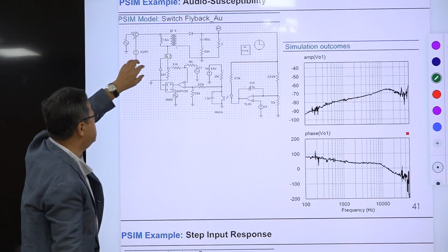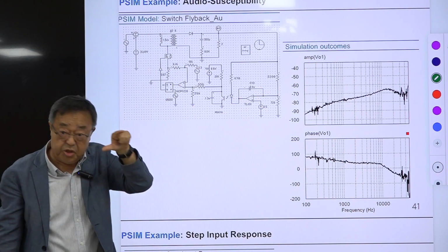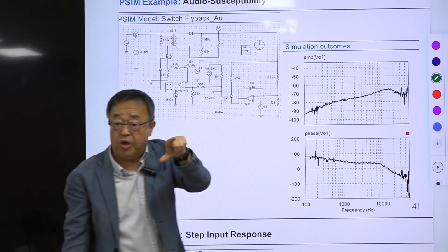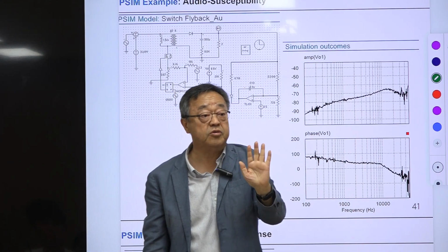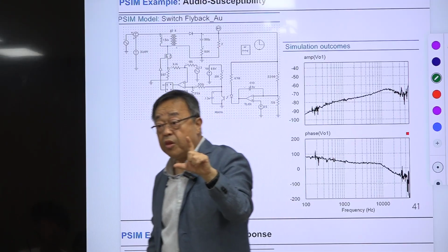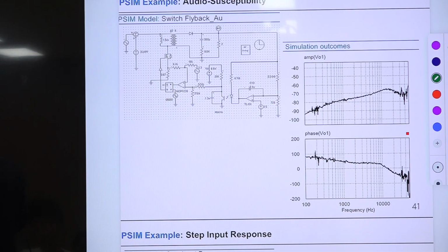Okay. Previously, the inject point and the measuring point, the input point of measurement, were different. So we used a two-port AC probe, but here you can use just one single AC probe. And again, this is the pole here. Then this is the omega GC, and the same thing. This is the loop gain crossover frequency, omega CR, right?